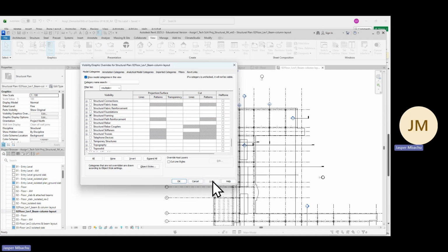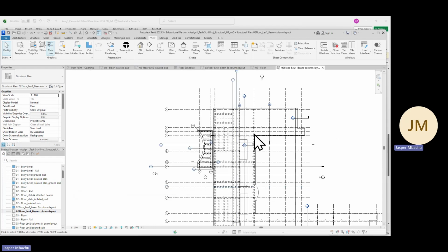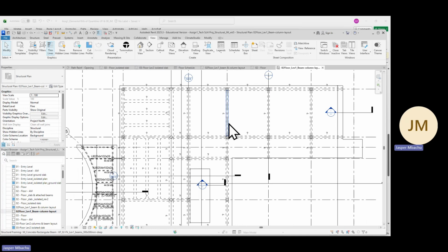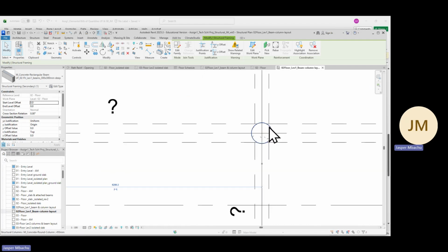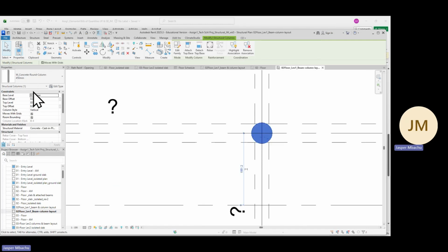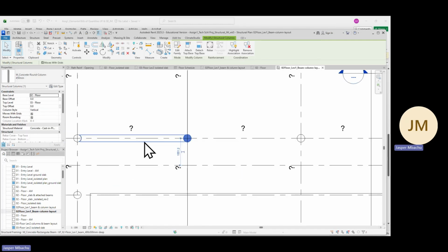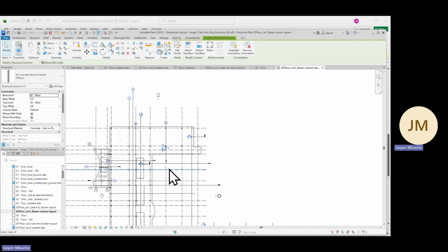So we click apply. You see they are showing here, and we click OK. Because when we selected those beams, even though they are beams, can you see next to the edit type, they are structural framing. That structural framing is what we use, just like we did in floors, to pull them out as the Revit schedule. And the other one we want to show is structural columns. So that's why we use the VGs to isolate them.